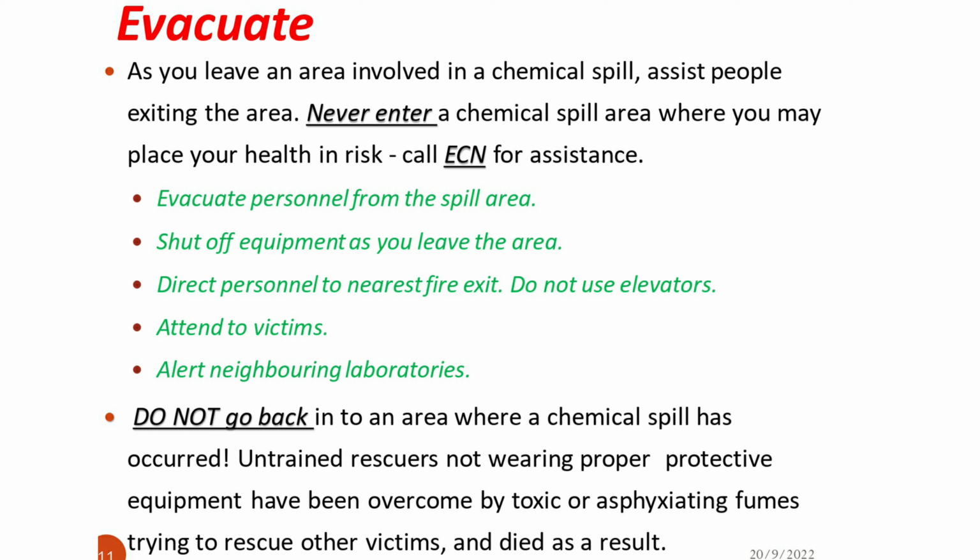Call for assistance. 1. Evacuate personnel from the spill area. 2. Shut off equipment as you leave the area. 3. Direct personnel to nearest fire exit. Do not use elevators. 4. Attend to victims. 5. Alert neighboring laboratories.